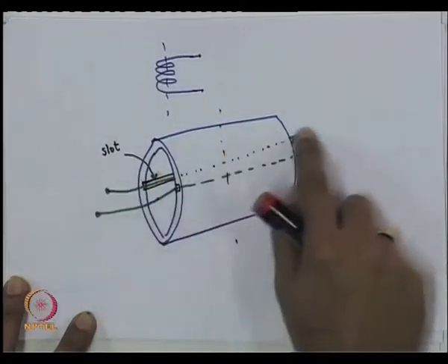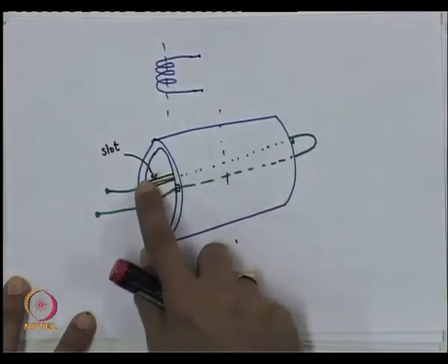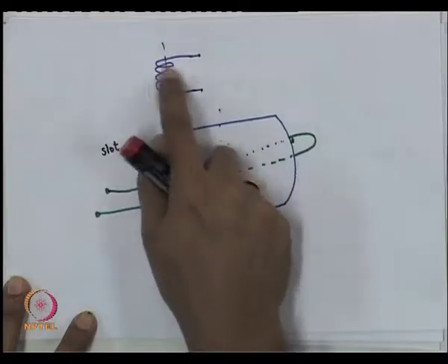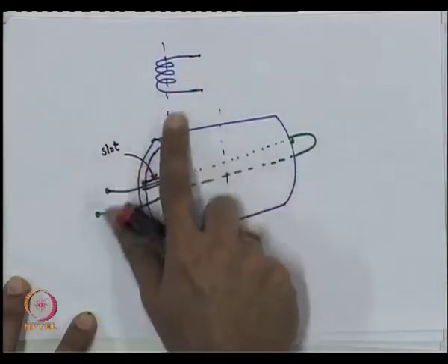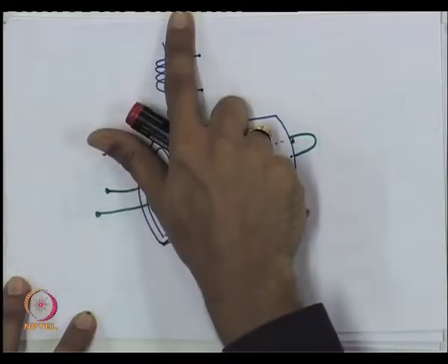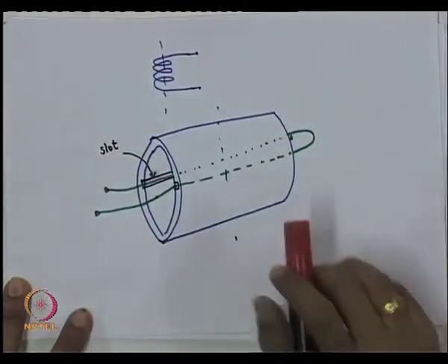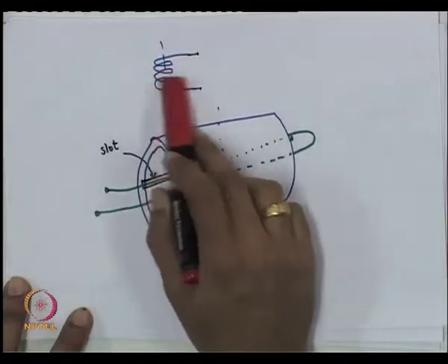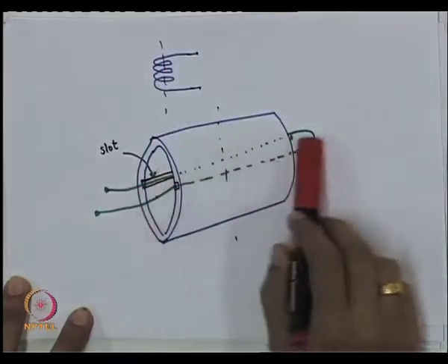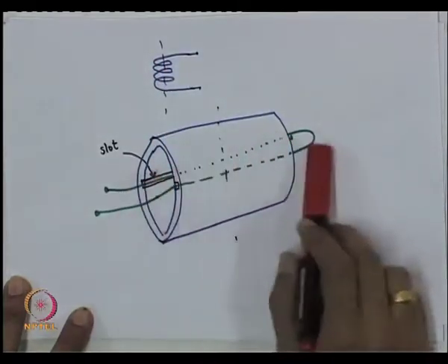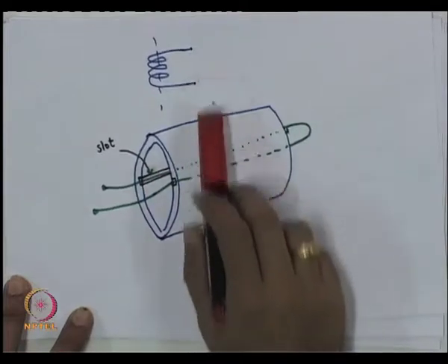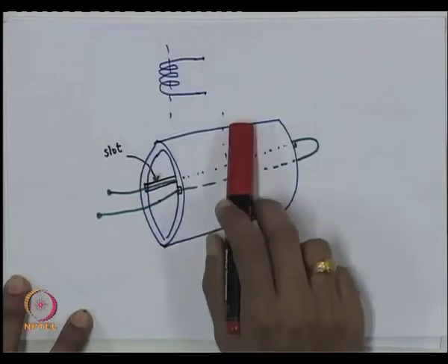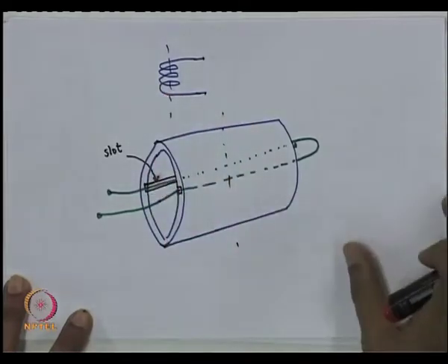This is just one winding. So, this winding is schematically represented like this and its axis is like this. Okay. So, this is what I mean by axis of a winding, and a schematic representation like this is actually implying a set of windings which are in this plane, and the flux they cause if current flows through them would be like this. Okay. So, this is what I mean by axis of a winding.